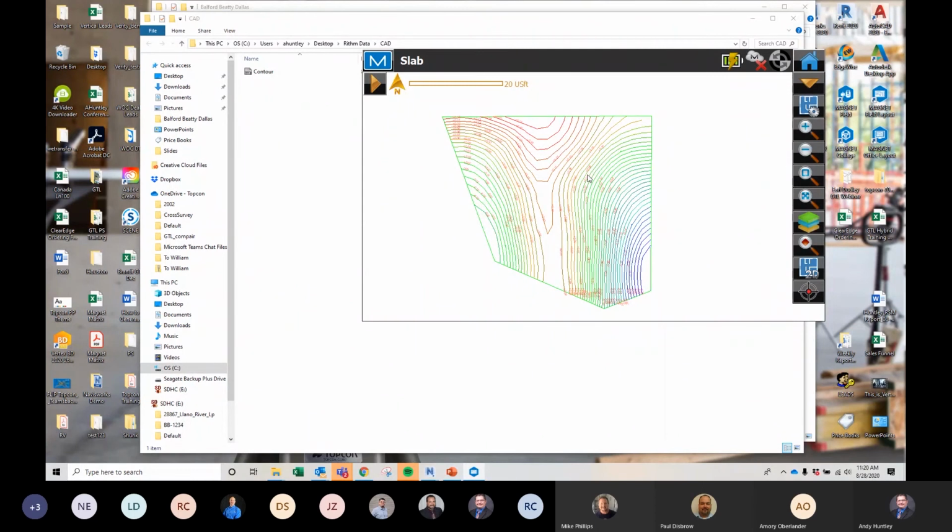And then if I had a laser pointer, instead of having a guy walk across the slab and sink into the concrete, I can just point a red point right on top of where that line is and say, hey, you're high here or you're low, like you're high over here and you're low over here, very quickly.